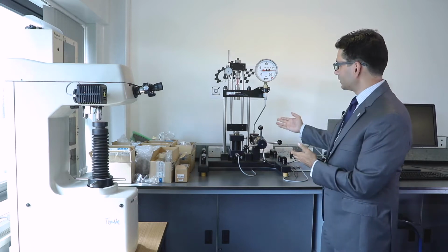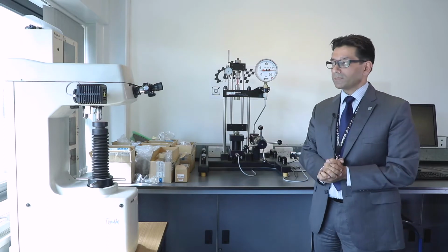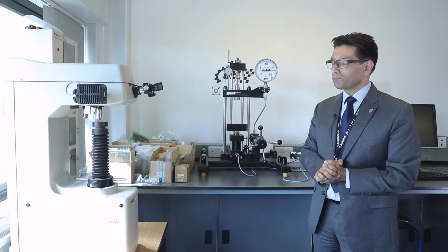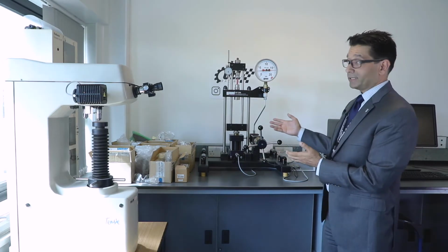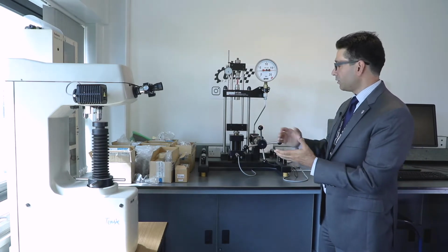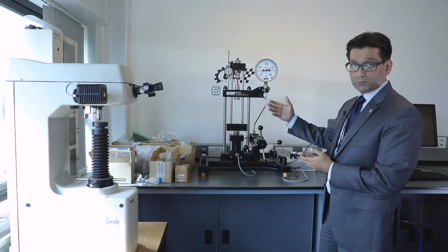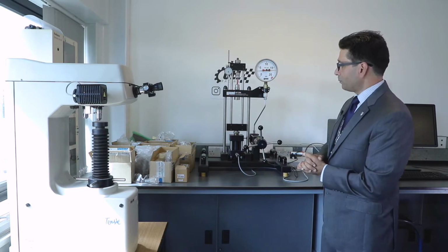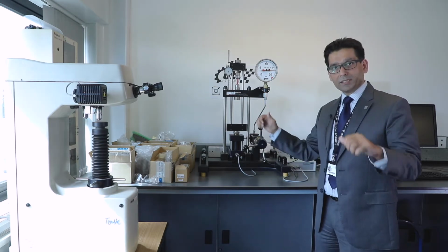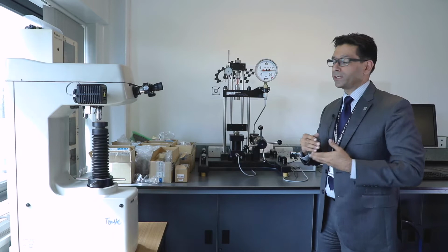In this section of General Engineering Laboratory, we have the universal material testing machine supplied by Gunt. And we also have the Japanese hardness testing machine. So the principle for the universal material tester is pretty straightforward. Our students, supported by the technicians, prepare the dumbbell-shaped specimen, or depending on the mode of stress they are going to apply, depending on the mode of forces, they place the sample once they achieve correct geometry in this machine, and they apply forces. It can be in tension, it can be in compression, it can be torsion, that's twisting, or it could be 3-point or 4-point bending.